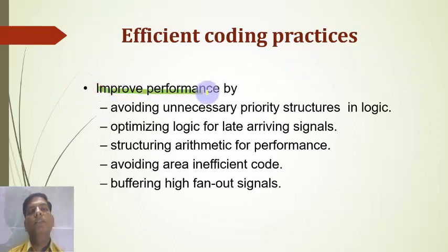Improve the performance by avoiding unnecessary priority structures in logic, optimizing logic for late arriving signals, structuring arithmetic for performance, avoiding area inefficient code, and buffering high fan-out signals.